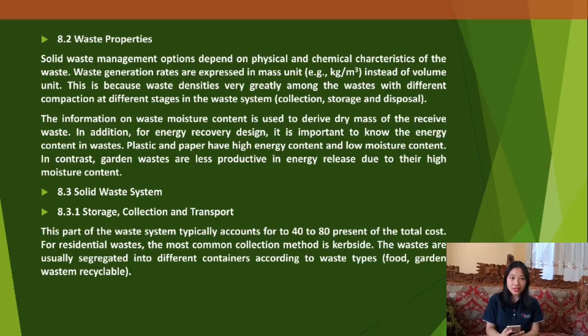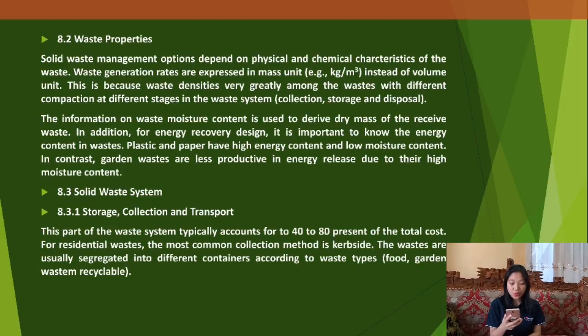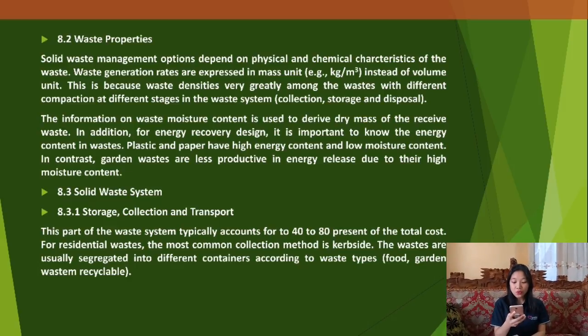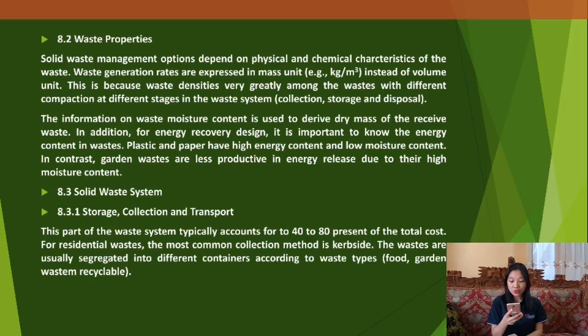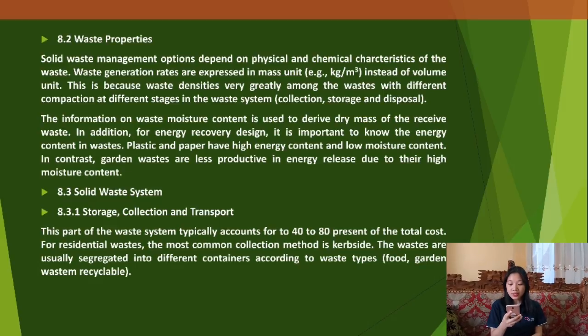8.3 Solid waste system. 8.3.1 Storage, collection and transport. This part of the waste system typically accounts for 40 to 80% of the total cost. For residential waste, the most common collection method is curbside. The wastes are usually segregated into different containers according to waste types: food, garden waste, recyclable.